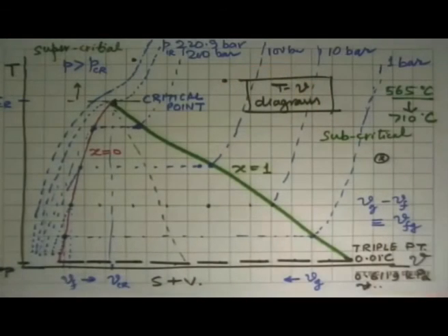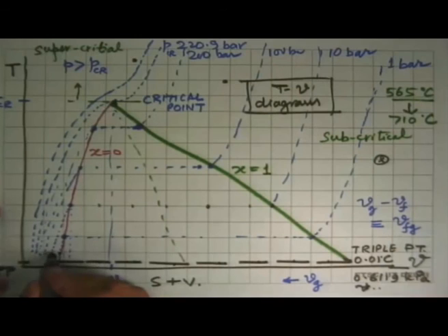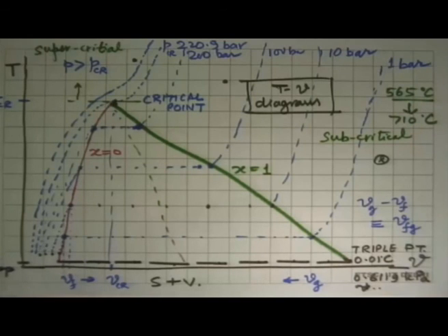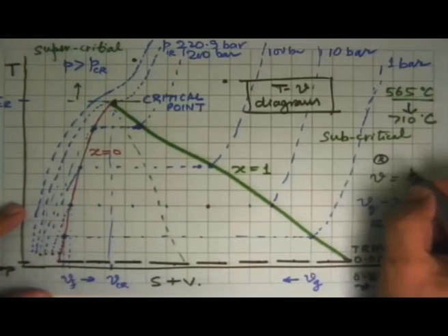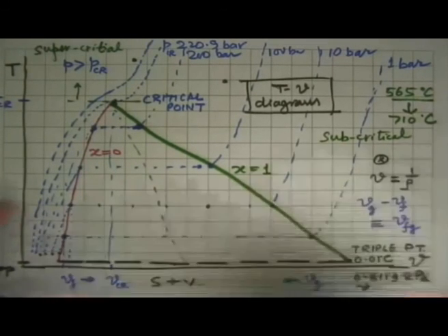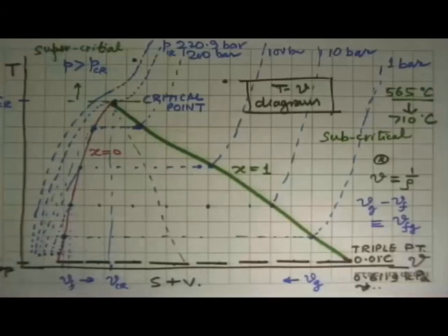Then there is another question. Why does the specific volume of liquid decrease as we increase the pressure? Okay. The question is, why are these points going like this when we increase the pressure? Well, if you look at it the other way, by looking at density, when you take water and compress it, its volume goes down. It becomes denser, so density increases, and specific volume is 1 upon density. So when you increase the pressure, the density has increased and the specific volume has decreased.